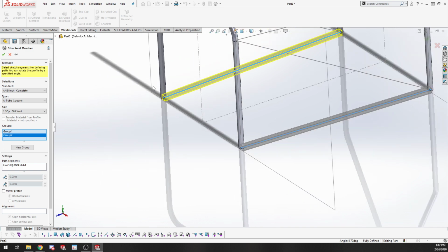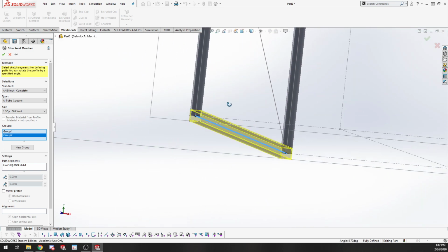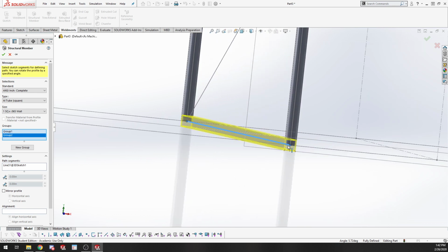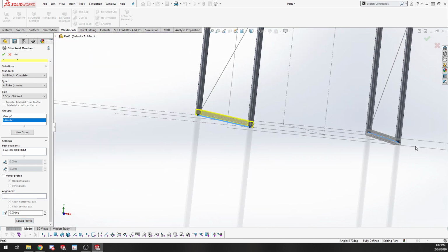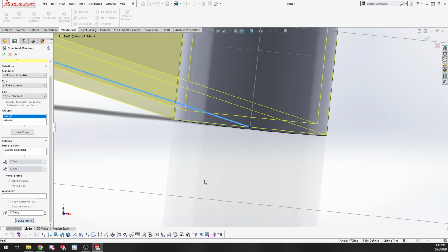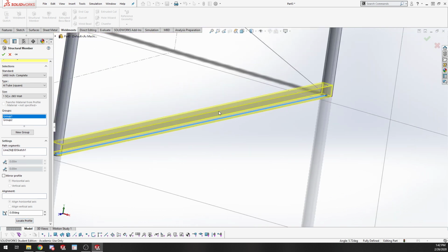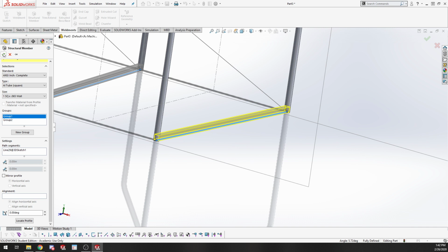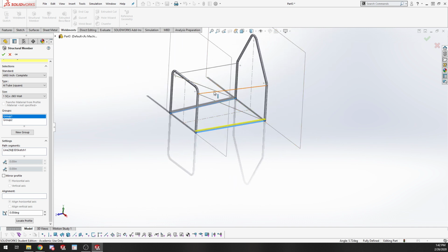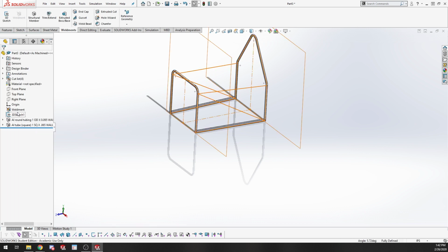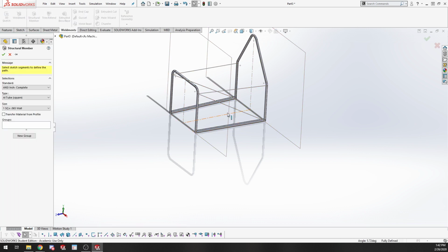And then I do actually want to locate these. As you can see right now, the center line's going through. We want that center line to actually be at the bottom here. So I'm going to locate the profile, bottom there, and same thing with this other one. Cool, so there's that. And then for the side impact structure, I think we use 1 inch, but it's only 065, so another different tube to use.